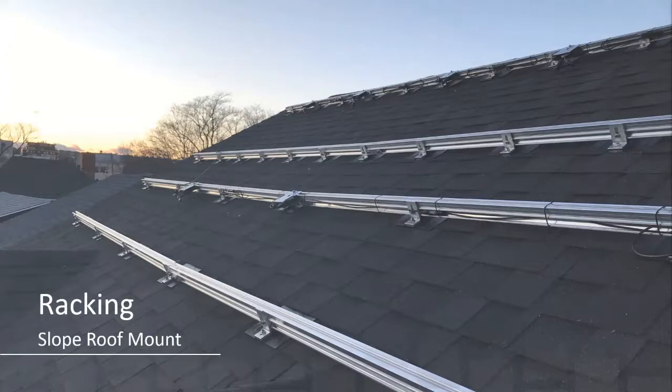Very simple to install. The products that are used in this marketplace have been well seeded for a long time, so they're fundamentally sound. They install very quickly, and really all you need are three main components. You've got a flashing kit, you've got your mounting bracket with legs into your rafter, you've got an L bracket coming up off of that, and then you've got the railing itself. And then on top of the railing, you would mount your microinverters and your modules. So very simple to install, very straightforward, most commonly used system in Atlantic Canada.